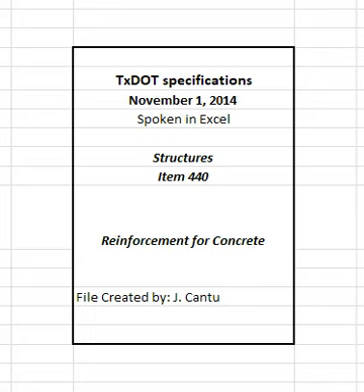2.9 Fibers. Supply fibers conforming to DMS 4550 fibers for concrete at the minimum dosage listed in the department's MPL, when allowed by the plans. Use non-metallic fibers when shown on the plans. 2.10 Stainless reinforcing steel.